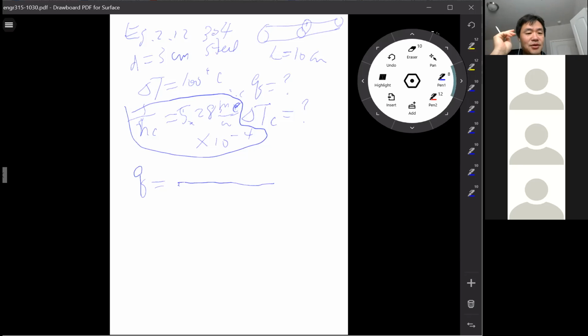Okay, I'm waiting on the equation. Can anybody give me the equation? It'd be delta T on top over RTH of the first bar plus RTH of the second bar plus RTH of the contact. Are the two bars the same steel? Should be, yes. How about just 2 times RTH of the steel plus the contact? That's good. Okay, save my writing.